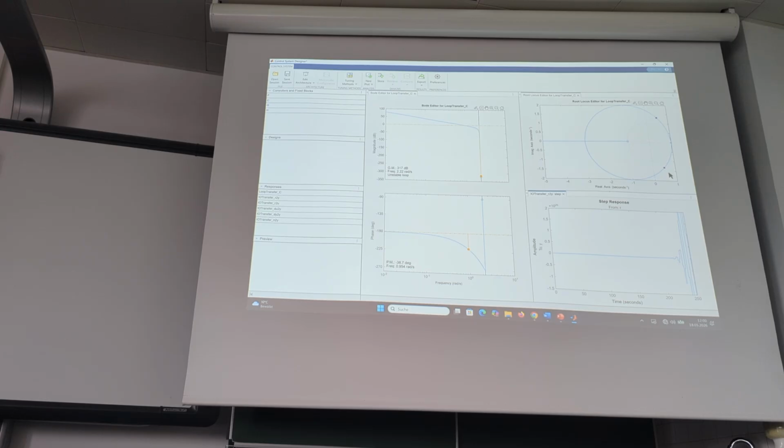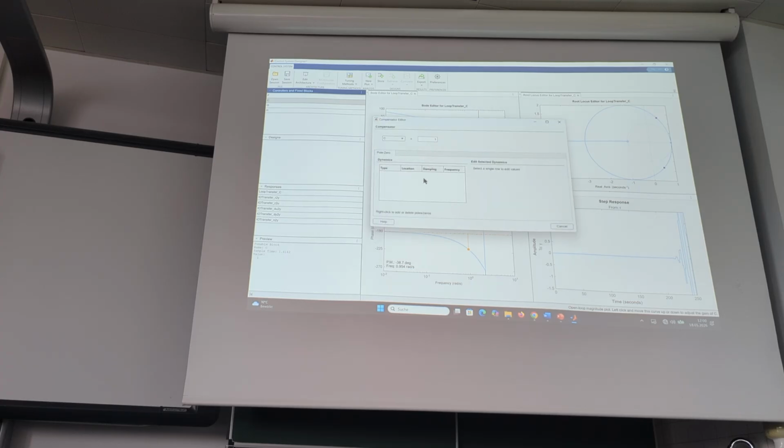The 2 purple dots are the closed loop system poles. We will not be able to get them into the unit circle with a proportional controller, so we make a double click on the controller itself and then add 1 zero, a real zero, and put it to the location +1.